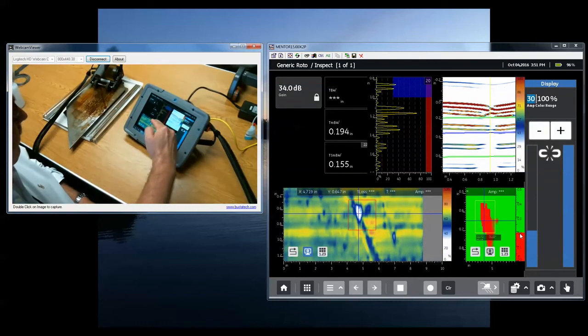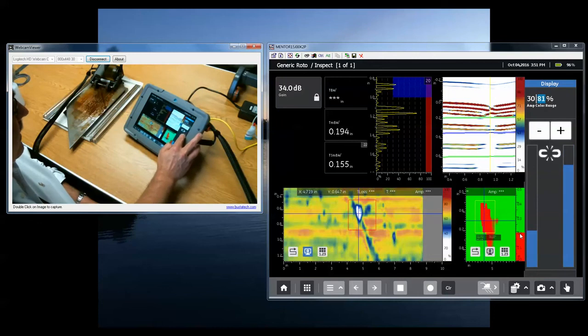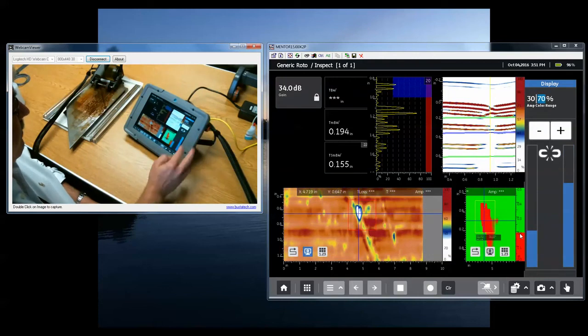now everything below 30% will be at the 0% color in the palette. All right. If I take the right-hand side of the control to 70%, now everything above 70% in amplitude, 70% full screen height in amplitude, will show in the most intense color, the 100% color of the palette.